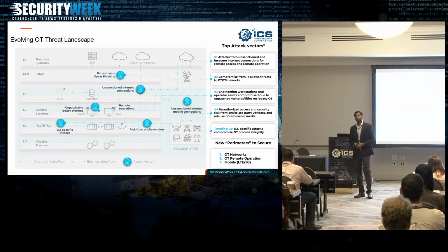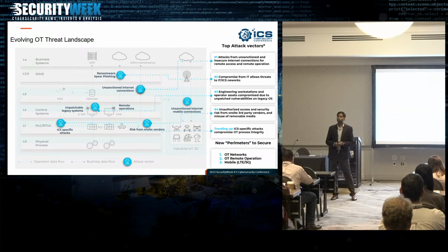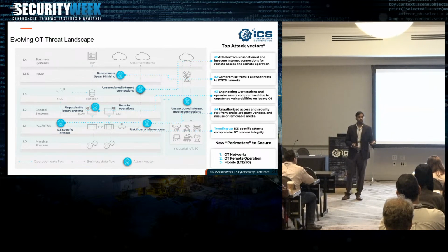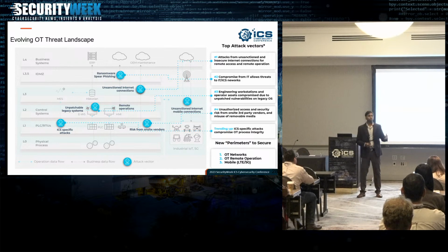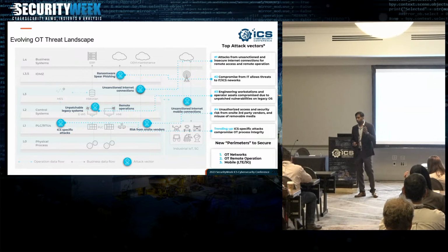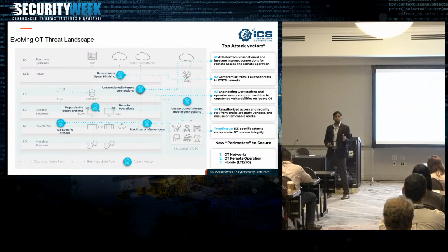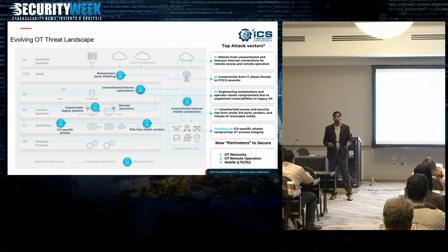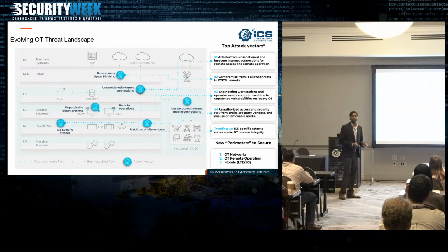The other set of issues we have observed within OT environments is ICS-specific cyber attacks, because most of these OT assets are pretty legacy. They have prolonged uptime. So we have seen Cosmic Energy, Industroyer, Stuxnet. These are some of the ICS-specific malwares that have been observed within OT networks, because you are not going to patch these since you really care about uptime.